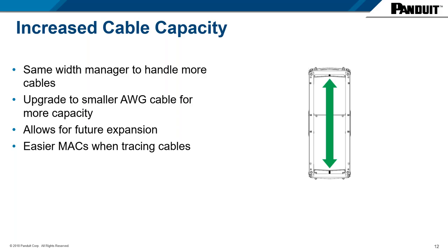As we mentioned earlier, you don't want to fill more than 30% on day one and no more than 50% on day two. So another nice benefit of the added capacity is it allows you to make easier moves, adds, and changes. With more capacity in there, it gives you more space.